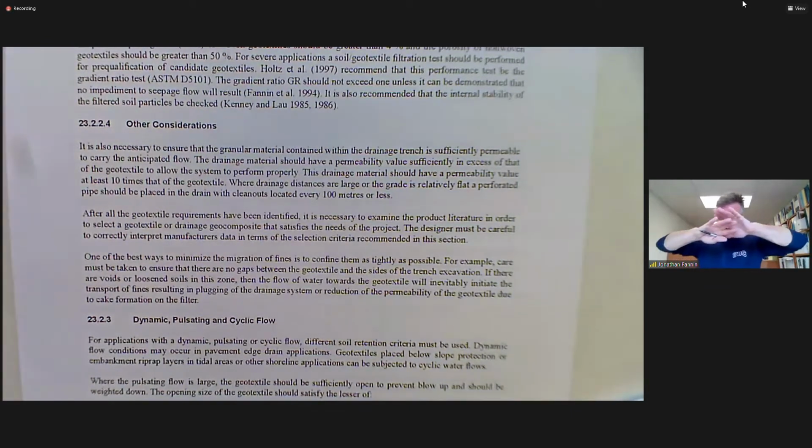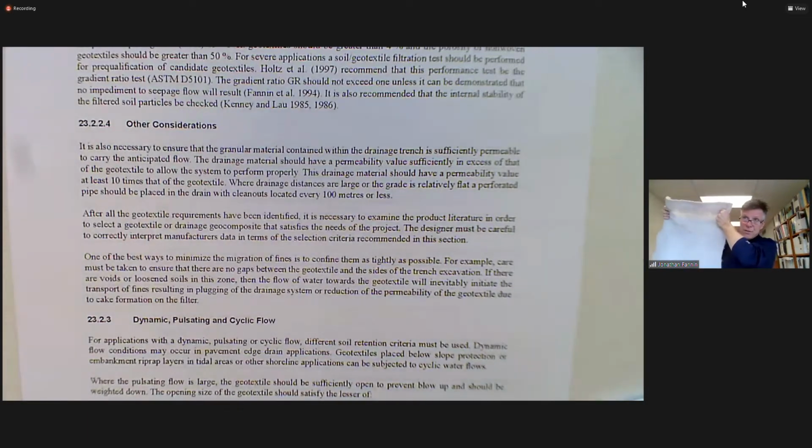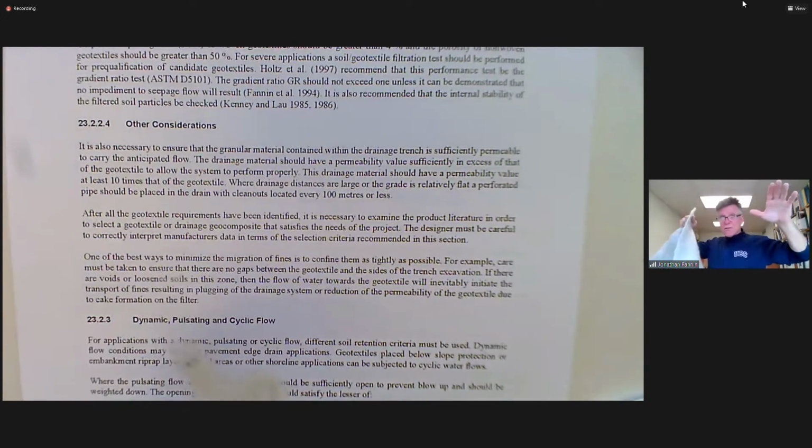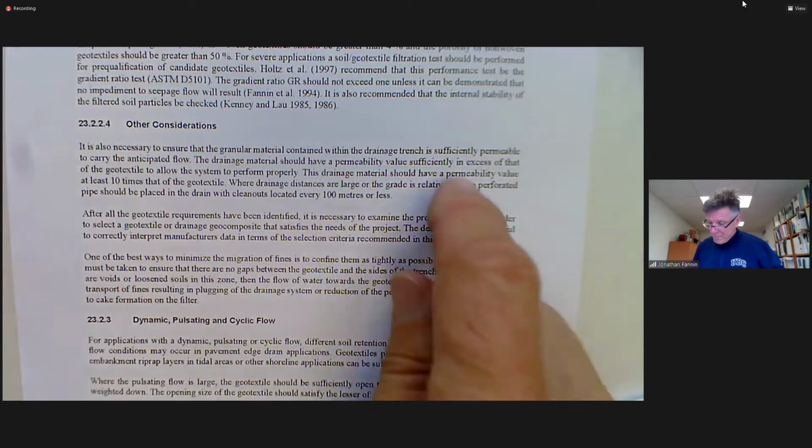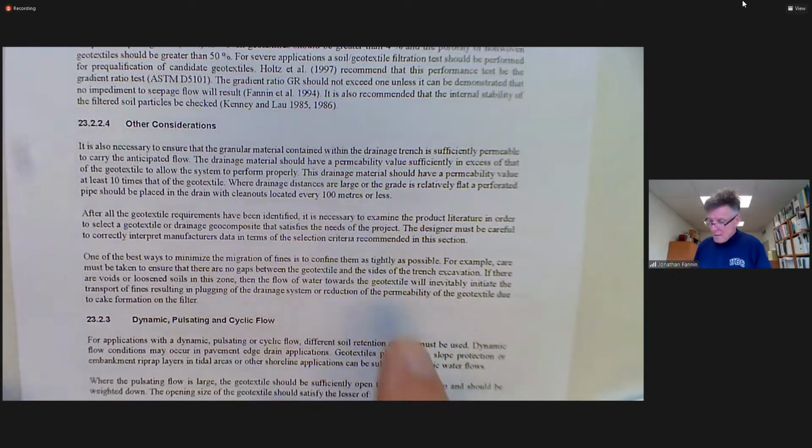The geotextile, because it's got tensile strength, can you imagine if your base soil is trimmed and prepped, but perhaps it's got undulations and so on, and you place the geotextile over the ground, the base soil, and the geotextile slightly in tension and being stretched, maybe the geotextile could stretch across a little bit like the surface of a drum. It could stretch across and actually not be in decent contact with the base soil, not in full intimate contact with the base soil. So there's a couple of comments related to that in there.